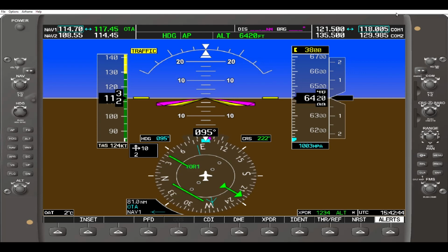So that was the panel of communication radios. Now if we move to the left hand side, we can see frequencies for nav aids. We can see two navigation radios, nav1 and nav2. Normally we use nav1 as our main source of navigation and nav2 as a standby. You can see it has the same principle. So in the blue rectangle is the standby frequency that we set with the knob, and on the other side is the active frequency. So we can switch them like this.